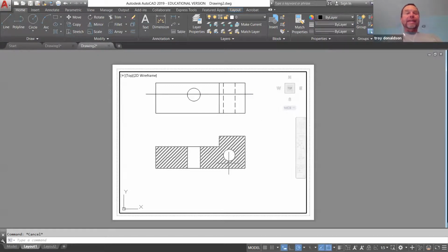Now, nothing happened, nothing changed. And that's because there's a line weight button, believe it or not. And it's down here in these quick buttons. So one of these is line weight. Show hide line weights right there. So I'm going to click that and it shows it.